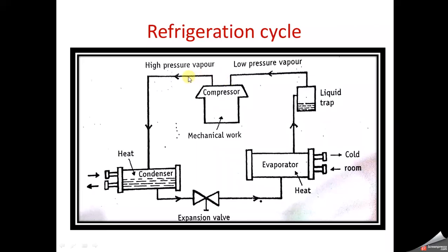The valve from here should be opened very slowly. A part of liquid vaporizes to give a stream of high velocity, like in the case of a pressure cooker. Once we release the valve, okay, what happens? Liquid evaporates at random to give a high velocity stream. Okay, so this high pressure vapor then moves to the condenser. So from here it is at high pressure.